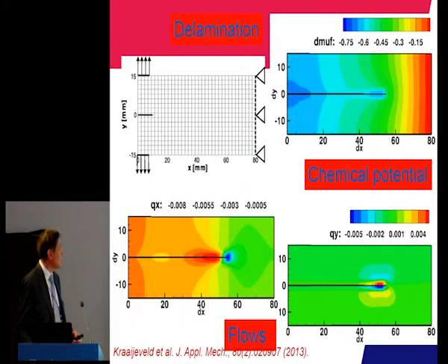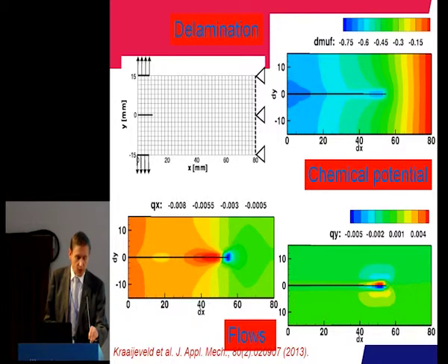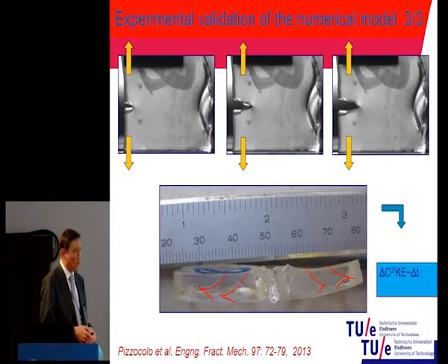In the XFEM approach, we can do an enrichment of nodes around the fracture and make sure that we can propagate the fracture through the elements. And we're going to do this for a poroelastic material which is swelling. This is a mode 2 calculation where we have both discontinuous pressure, or chemical potential, I should say, and displacement, and we have an initial fracture here, and we're going to push from this side and cause a mode 2 fracture along this line.